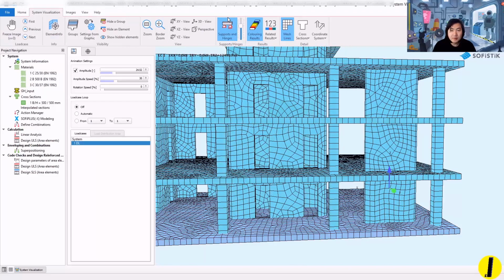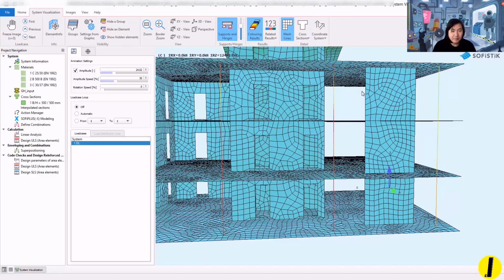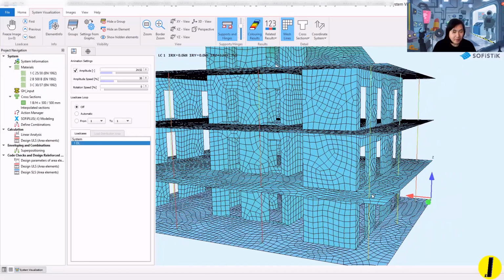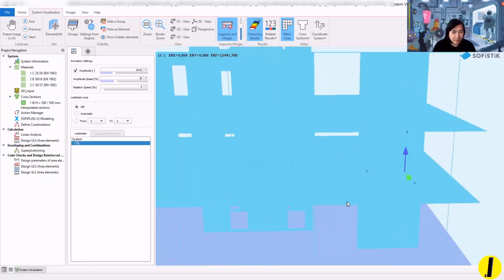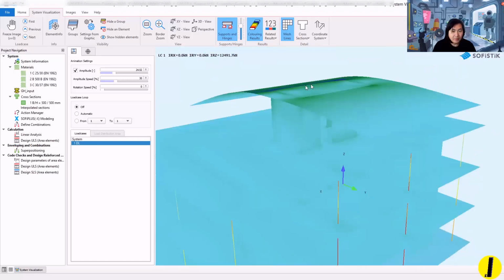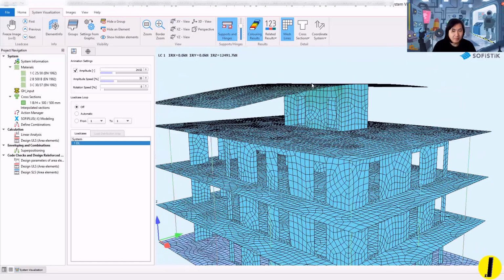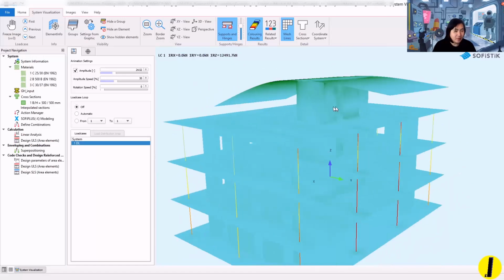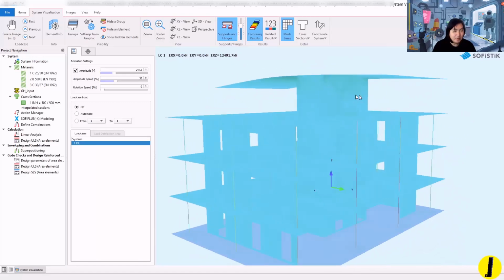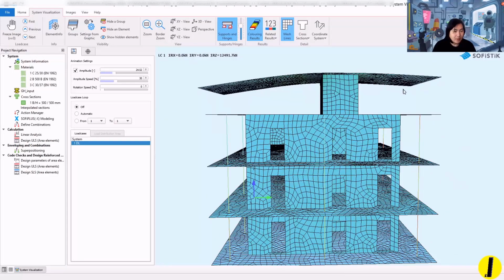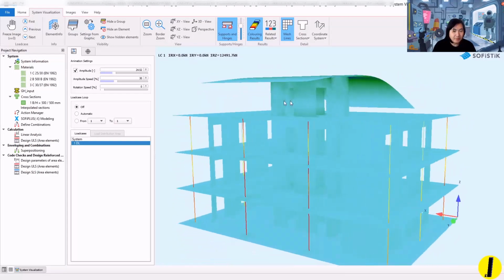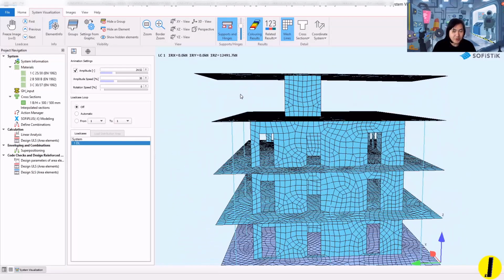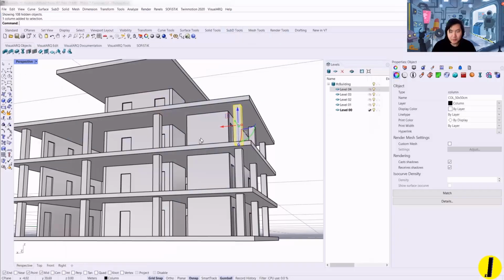I'm just going to make the slab thin here, so there is almost no impact on the structure, and the roof is quite weak, as you can see from this view. So by referencing this, I want to modify the original IFC model, and then we can calculate a bit better result. So let's go back to Visual Arc.